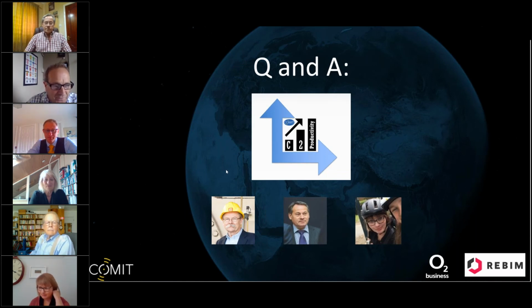Balfour Beatty Dartford Free Flow Project 2012, we used 3D GPR and processed into 3D, and then used for clash detection for the design coordination against survey, and had 974 high potentials which were programmed around or diverted. 3D is the way to go with PAS 128 and PAS 256 data requirements.